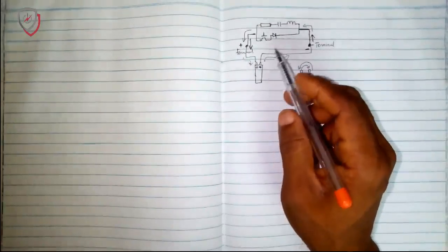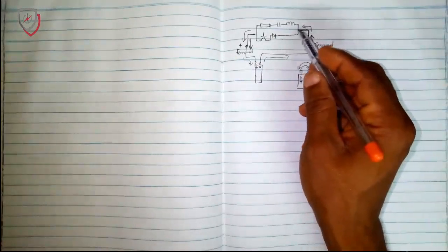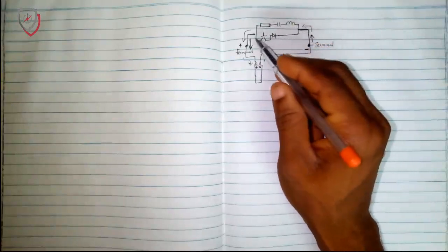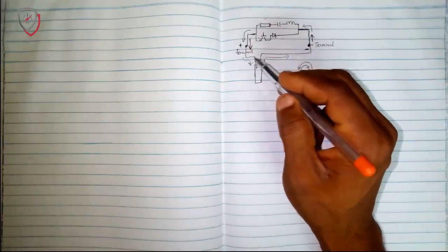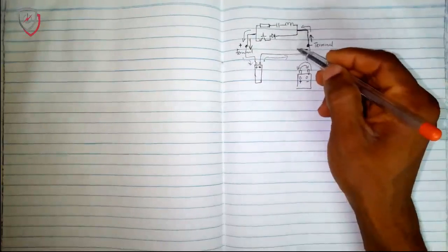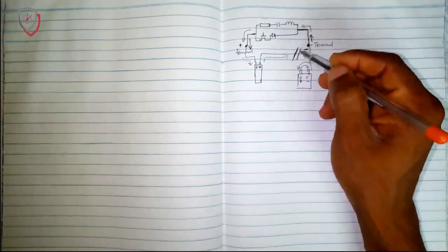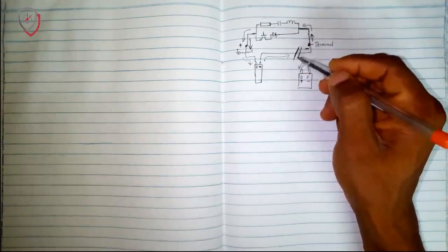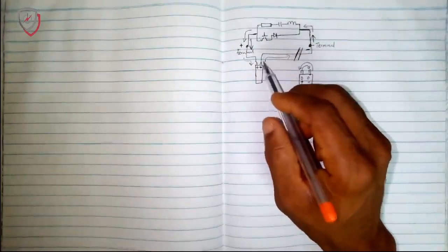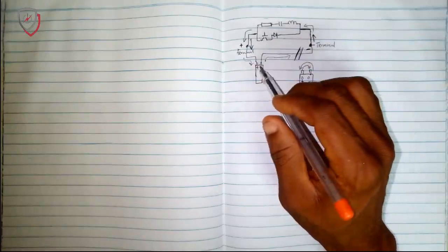You can see that there is a continuous line of flow. It can pass through this place, get to here, or it can pass through here, but it will always find its way back to the battery. Let's imagine something happens to this line here and it cuts. There becomes a bridge or an opening. An opening happens here. There will no more be current flow. Current will no more flow from the battery through the circuit and back to the battery.